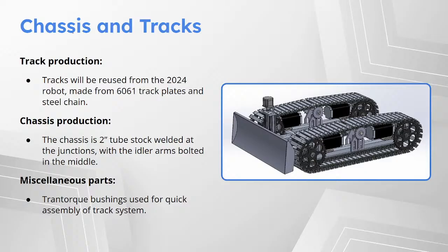Now, was that FEA done on how dense was that mesh, and was it done with only one spoke, or was that applied to all? I applied it to all of them, and the mesh was pretty dense, I want to say. When doing FEA, it's best to apply the whole load, divide the torque by the number of splines, because then it's applying the load per tube, not the entire load all at once. I also did the shear calculations for the minimum cross section on the spokes by hand as well, just to double check it.